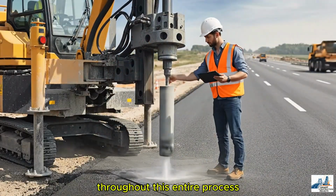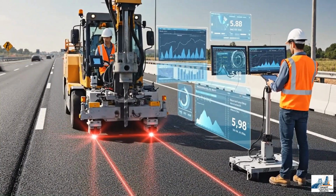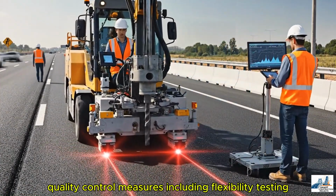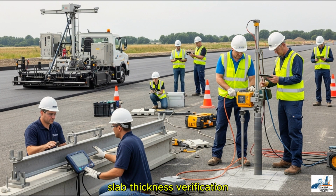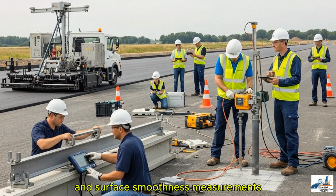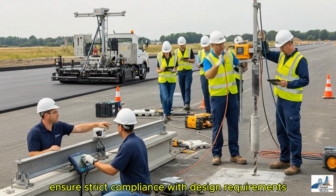Throughout this entire process, verification remains continuous. Quality control measures, including flexural strength testing, slab thickness verification, joint alignment inspection, and surface smoothness measurements, ensure strict compliance with design requirements.